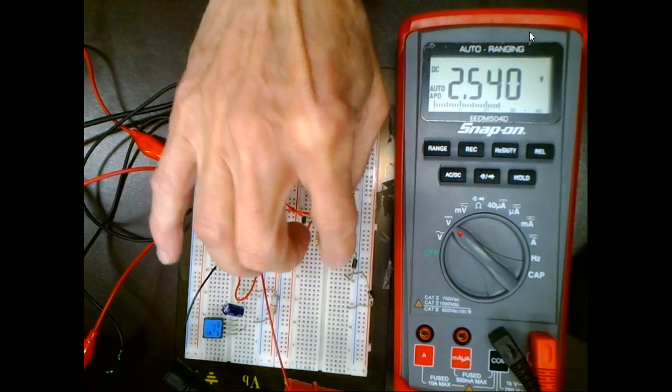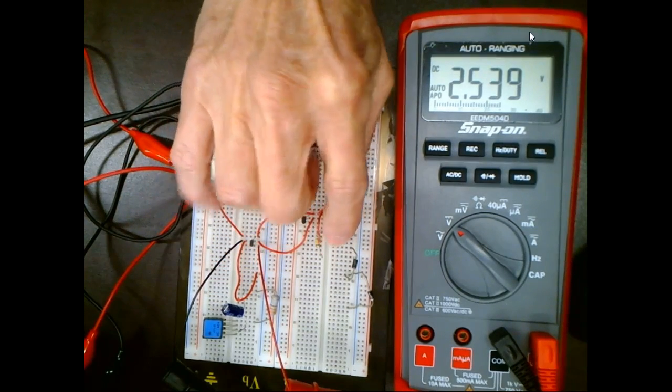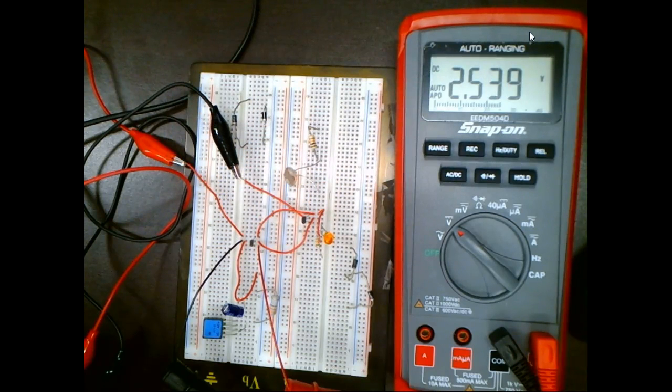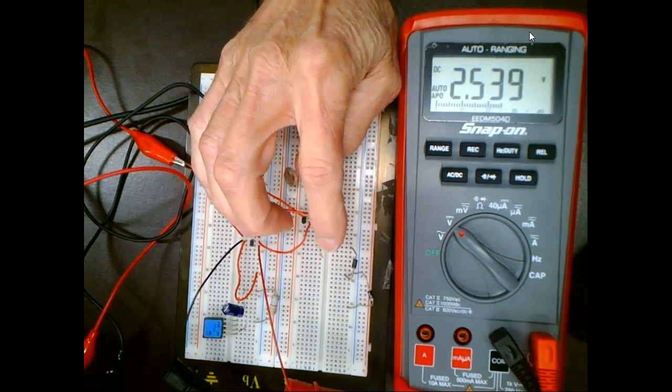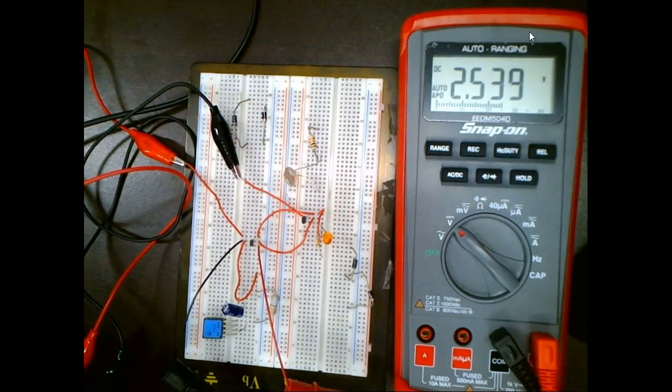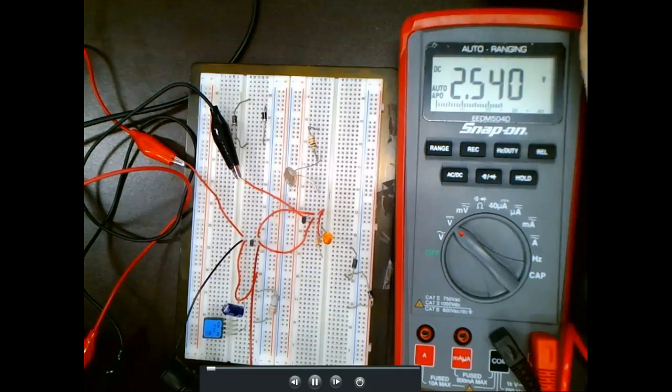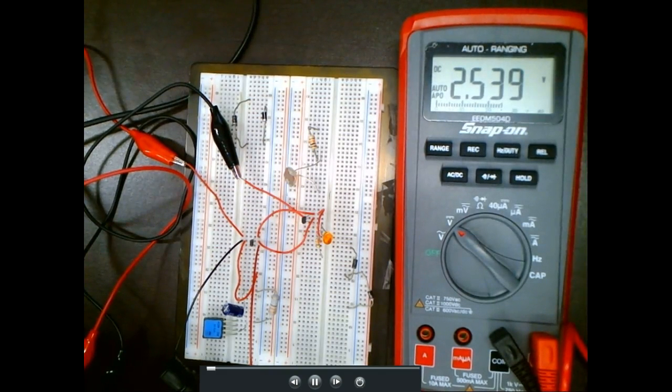This guy here, I've got it set up to, I think, 10 milliamps. I'm using 10 milliamps to turn the LED on. Rule of thumb, the maximum current in most LEDs is 20 milliamps. So you need to run it below that, but you need to have it so it'll come on. What's nice about LEDs though is once you turn them on, you can control their intensity by how much current flow you put on.